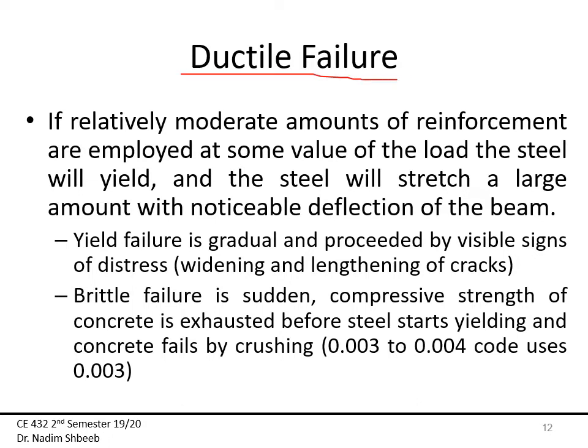Now, ductile failure. One of the things that I want to emphasize that we usually enforce is that in flexural design, I always shoot for ductile failure. Why do I want a ductile failure? Well, ductile failure means that the failure is not going to be sudden. You are actually going to see the beam starting to fail by showing some large deformation, and that will give you at least some warning, either to clear the building or do some repair to fix the problem, so at least you will have some time to do that.